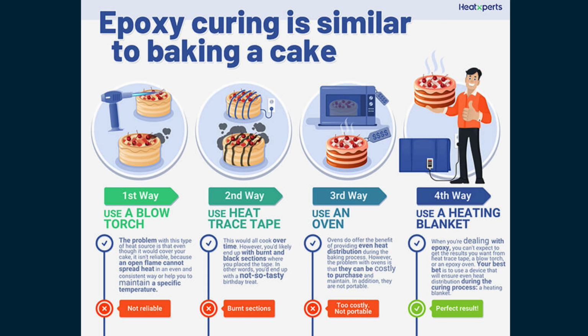Conclusion: epoxy curing chemistry encompasses a wide variety of mechanisms and curing agents, each providing unique advantages and limitations for adhesive applications. Aromatic amines produce highly cross-linked networks with excellent thermal and chemical resistance but require elevated processing temperatures and may present toxicity concerns. Acid anhydrides offer long pot life, low exotherm, and high heat resistance, though they require catalysts and elevated curing temperatures.